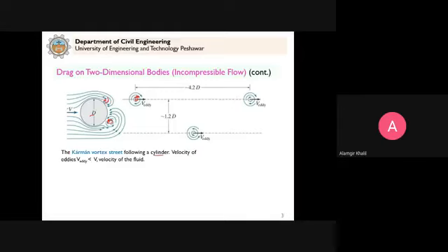These vortices shed from the body surface and continue to flow downstream. First this phenomenon occurs on one side and then it is followed by the other side, clear. These vortices form, shed from this body and continue to flow with the fluid. This arrangement is an approximation, given that the distance between the two is 1.2 times the diameter and so on.